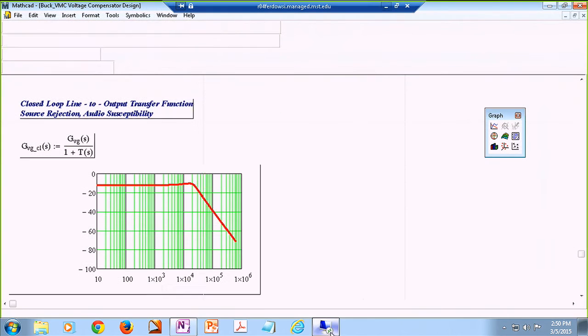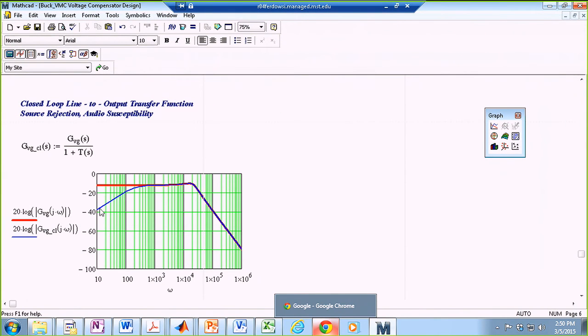All right. So I'm actually looking at them as well. You can see that adding an integration block, the red one is the open loop. The blue one is after you add an integration block. Now, remember, we want this transfer function to be as small as possible. Ideally, we would like it to be 0 or negative infinity dBs. So the closer that I am in these negative territories, the better it is. You can see this integration block for a little while does a good job, because if I continue this to the left, this blue curve gets more and more negative, which is very good actually.